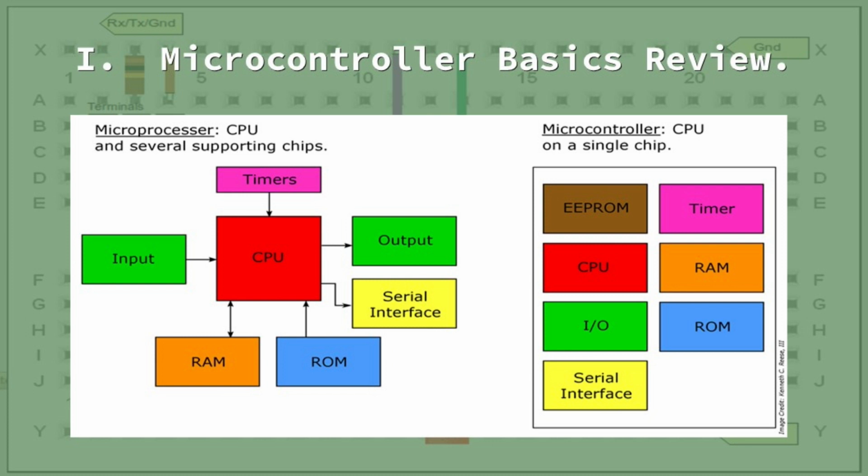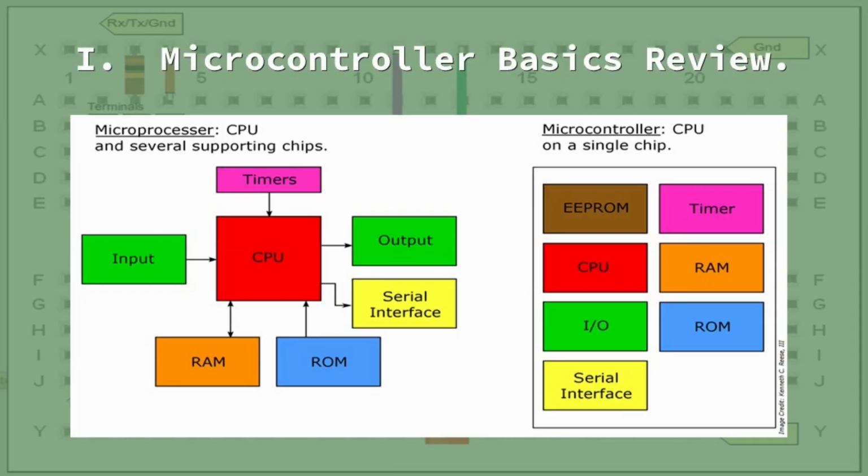As a matter of fact, with the Raspberry Pi Pico, you're going to find this to be amazing. The actual chip itself, the RP2040, has its program memory external. But on the Raspberry Pi Pico board, it's on the board. So you can have external memory, but they put it on the board for you to make it easier to develop. I apologize for not having the Raspberry Pi Pico program ready, but with everything going on, I've not had time to finish it. And you can see the microcontroller has it all literally in one die, in the silicon real estate. That way you don't have to go out and buy these extra pieces.